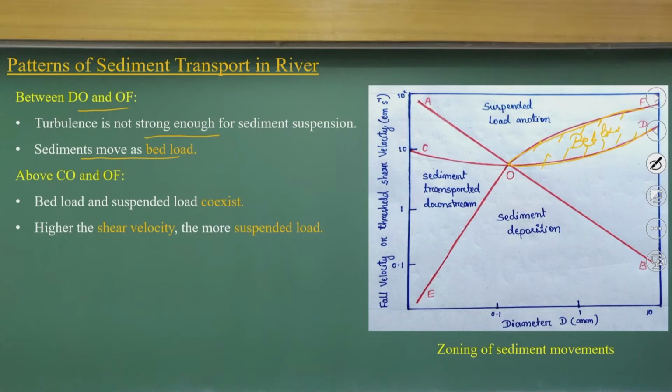Okay. Beyond this curve, above CO and OF, the bed load and suspended load coexist; the higher the shear velocity, the more the regions fall within the suspended load.